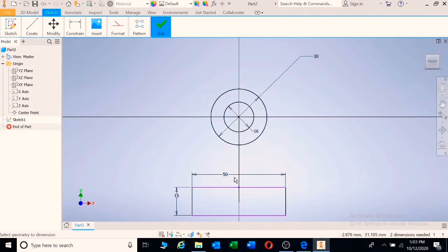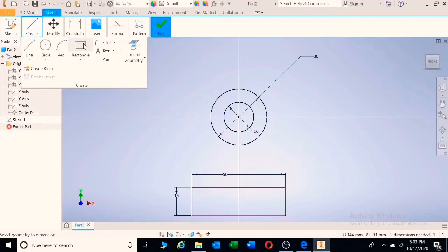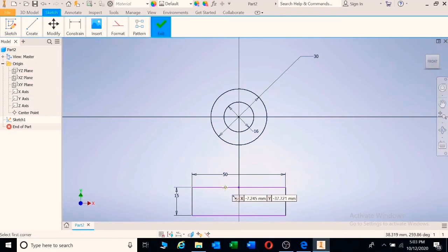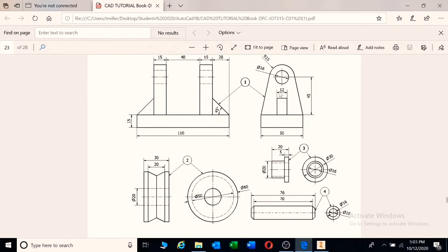Remember, this is not your actual manufacturing drawing, so you can just put down your dimensions everywhere. You don't need to put it in the center. Another rectangle there. Let's go look at the size of the rectangle. We've got 12. If we go straight across, we're having a height of 45 there. So we've got a width of 12 and a height of 45. If that is 20, and this is 45 degrees, then that will also be 20 millimeters. So it's 20 by 12.